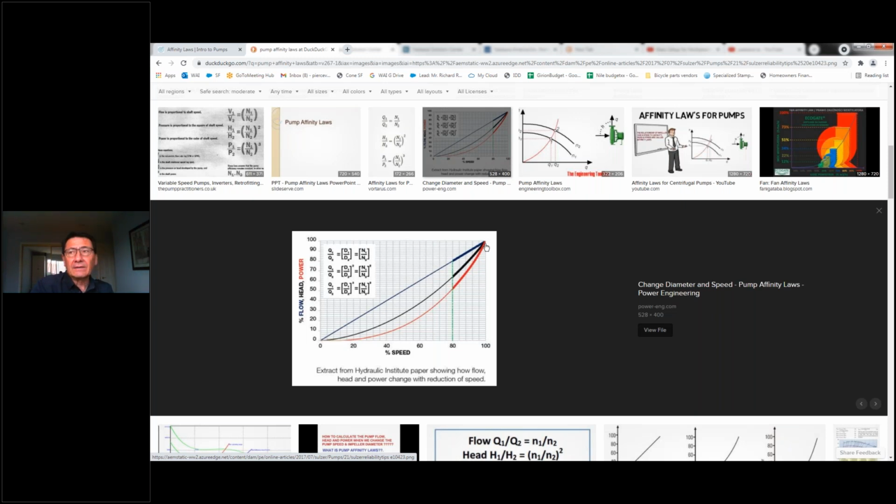The torque on that, if it's an 1800 RPM motor, happens to be about 300 foot-pounds. If it's a 3600 RPM motor, it's about 150 foot-pounds. But for this discussion, we're really not concerned about torque. We're talking about energy savings of power. So let's, for the rest of this discussion, eliminate this black line and focus on the red line.